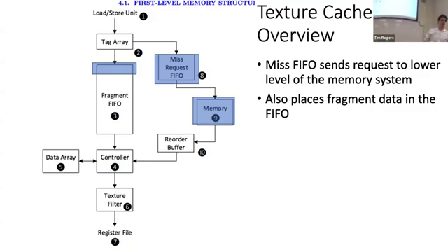And the hope is that the stuff is back from memory by the time you get there. If it's not back from memory, you have to stall the FIFO. The whole thing has to wait, right? Because it's possible that there's some disaster in memory that makes it take longer than the size of your FIFO that you had. But we size this such that in the common case, it's usually back or very close to back.